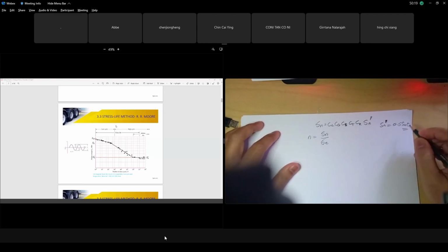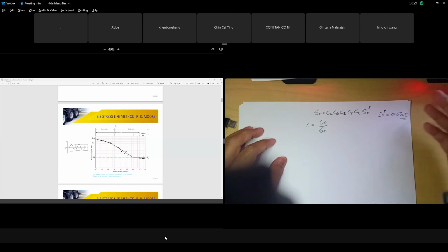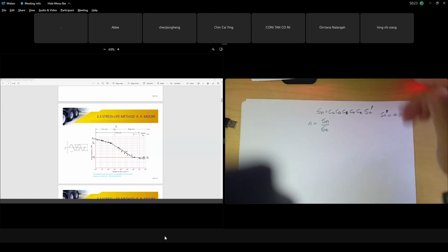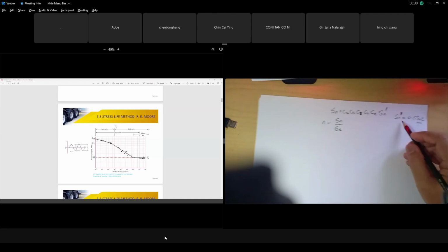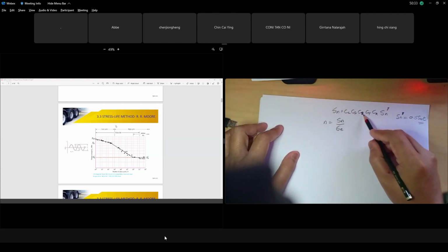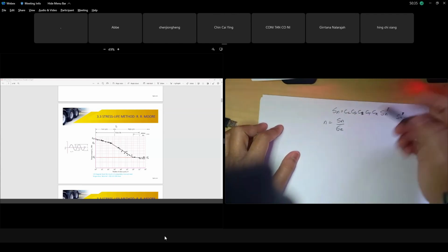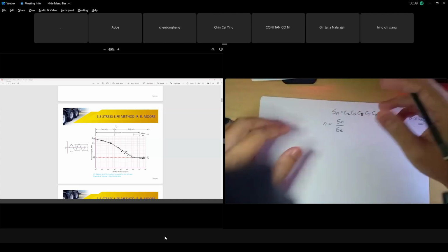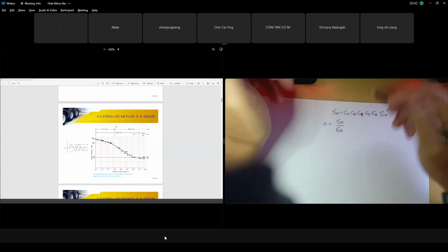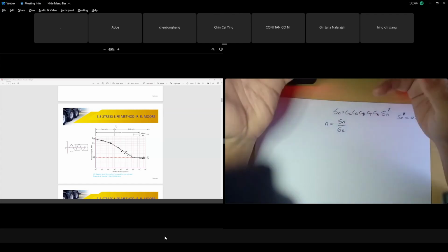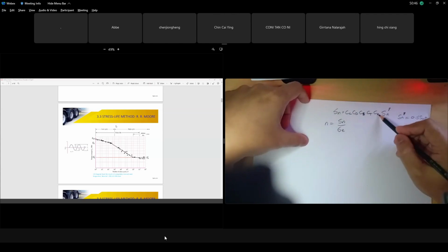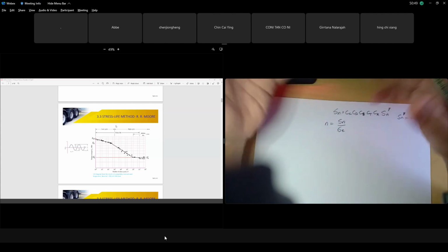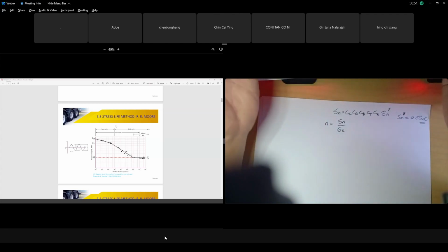Because your SUT you can get from the table of material properties at the back of your textbook. For AISI 1020, search for the tensile strength, not the yield strength. Then you get your SUT, the tensile strength, times 0.5, that is your SN prime. Then you multiply by the modification factors. It is easy. CL, load factor, for bending is 1. CG, gradient factor, for shaft diameter. CS, surface factor, look at the shaft's surface finish and you can get the factor. Temperature factor is based on the temperature during operation. Reliability factor, if given 99%, use the factor for that; if not given, we go for 50%, which is 1.